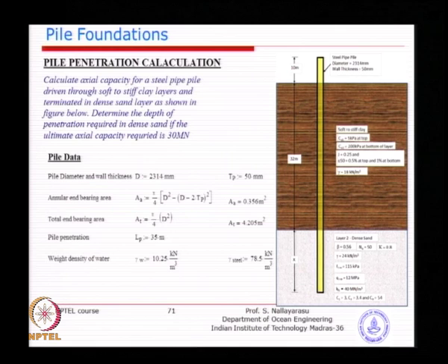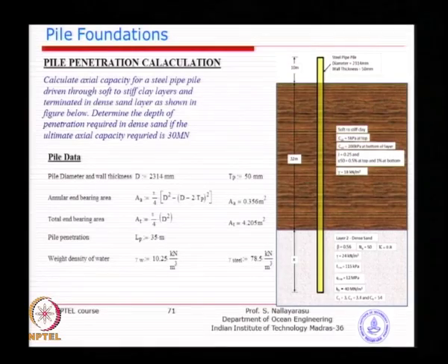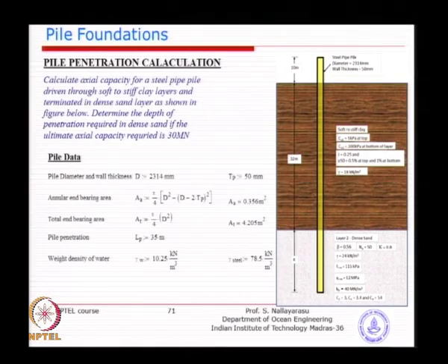So, you can see the strength is varying in this fashion because of a sedimentary deposit, which we discussed earlier on. As the deposition keeps happening, the bottom of that particular layer, especially the clay type of material, gets consolidated and gets better and better over the years. So, this layer has a linearly varying strength. Most of the time you will see clay type of material varying non-linearly, but for ease of solving this particular problem, I have given linear.